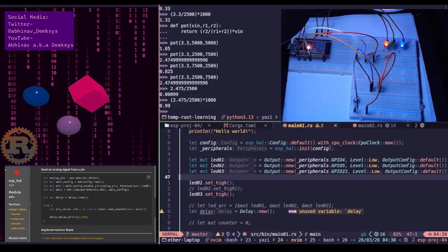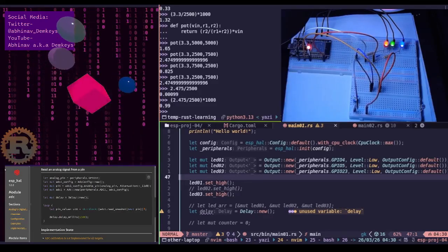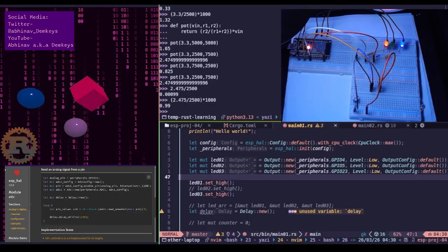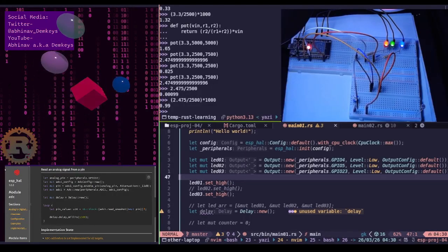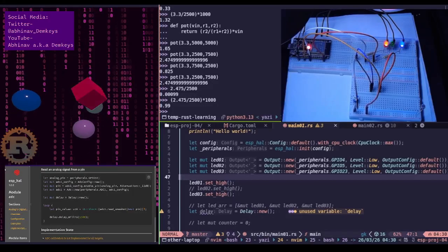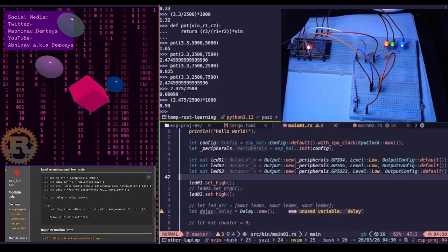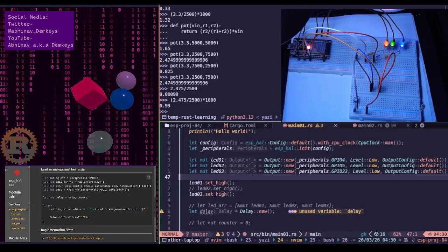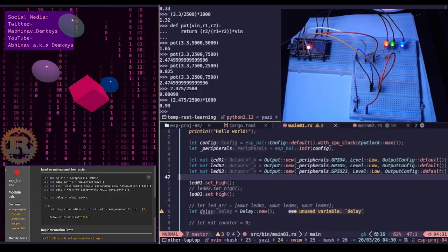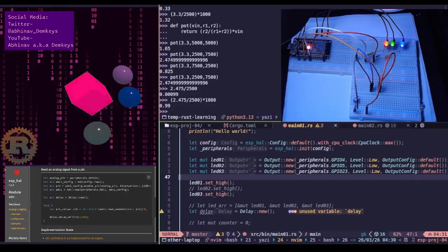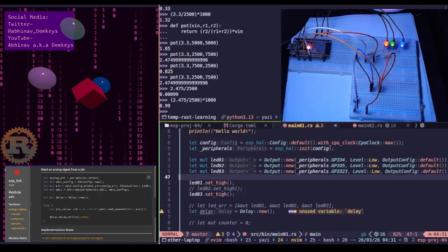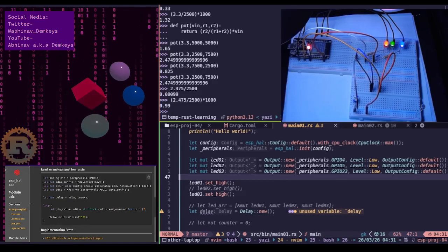Okay, the short answer: the ESP32's internal ADC is actually quite fragile when it comes to voltage. Left to its own devices, it can only "see" signals up to about 1.1 volt. Since your potentiometer is swinging all the way up to 3.3 volts, you have to use an internal attenuator to shrink that signal so the ADC can understand it. Okay, okay.